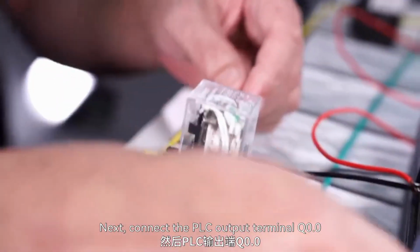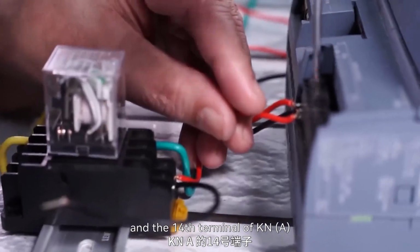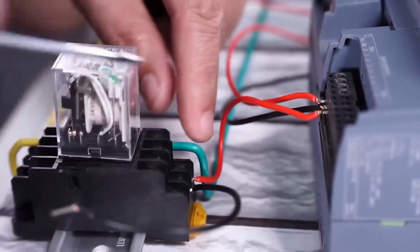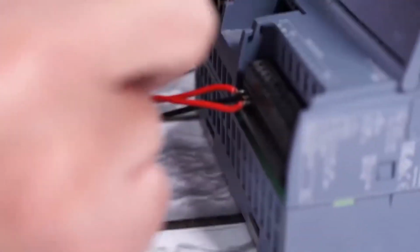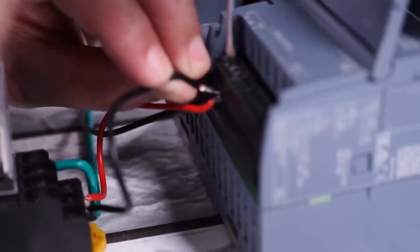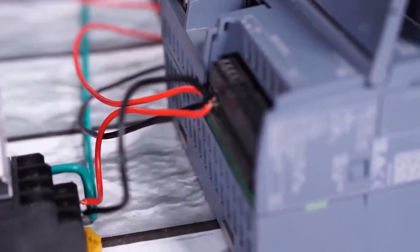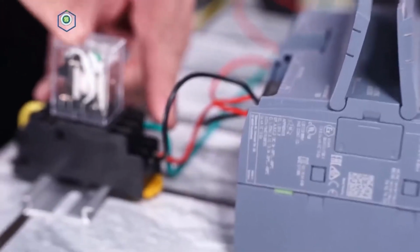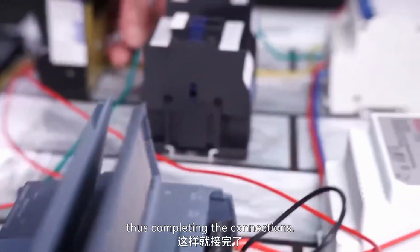Next, connect the PLC output terminal Q0.0 to the 13th terminal of the DC device KA and the 14th terminal of KA to the negative power supply 4N. By controlling the on/off state of relay KA with the PLC, you can control the AC contactor coil through its normally open contact, thus completing the connections.